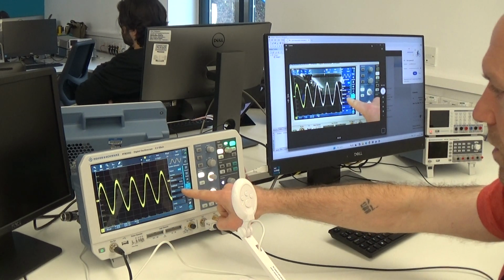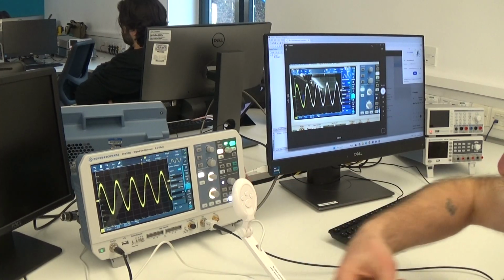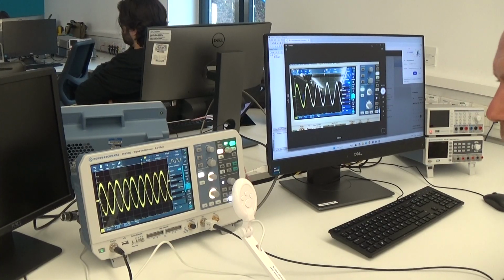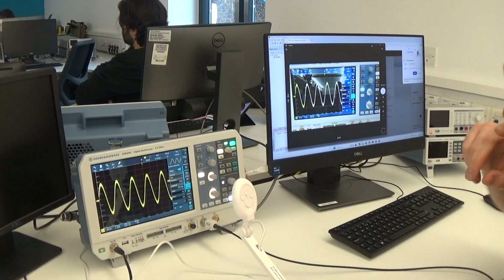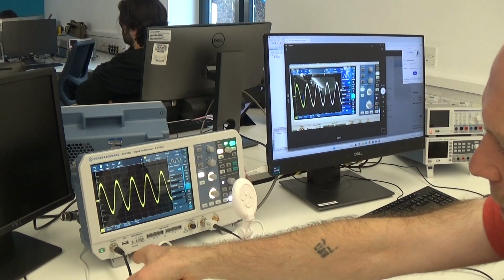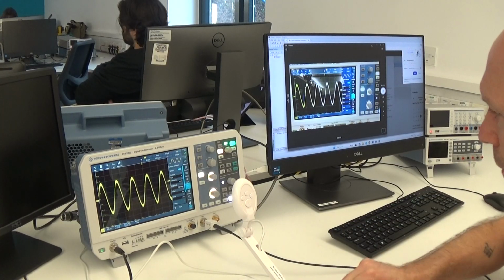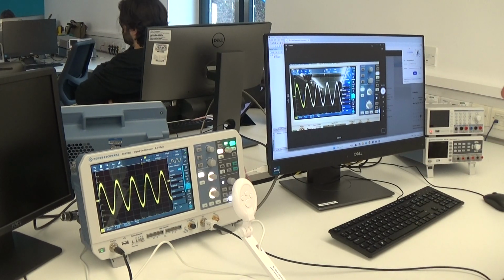We are showing a 250 millivolt peak to peak, but we have some loss in this cable, and the frequency that we're running, and potentially the world's worst probe. So unfortunately there is some loss there, which is represented by the amplitude being somewhat reduced. Potentially a mismatch in the output impedance of this will be 50 ohms, and then the input impedance of this probe will be 1 meg ohms. So there will be some loss there.